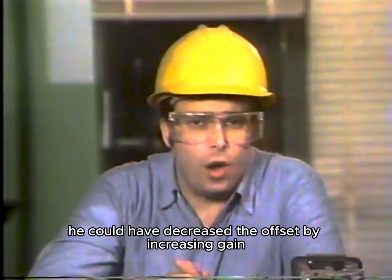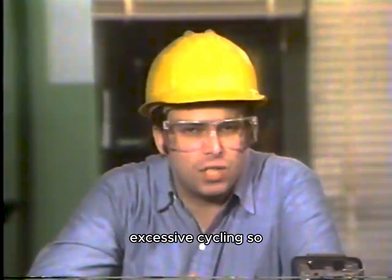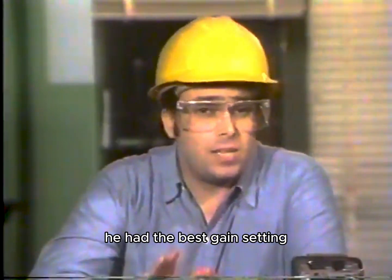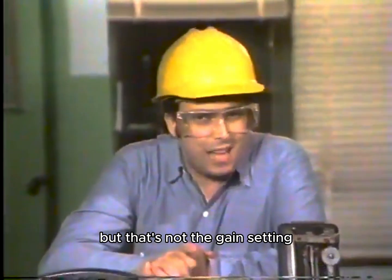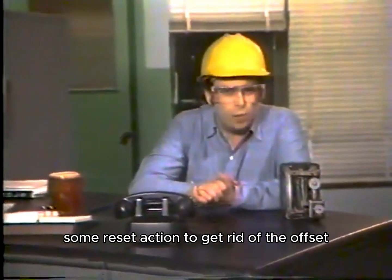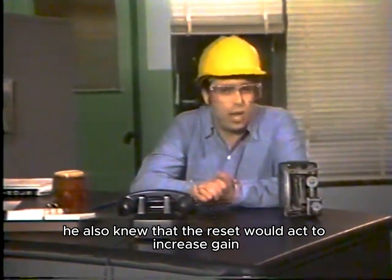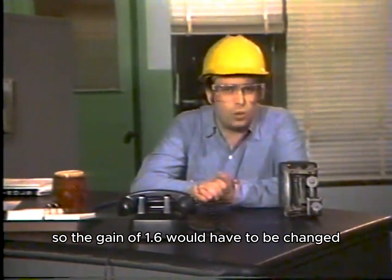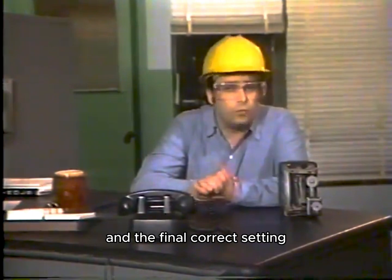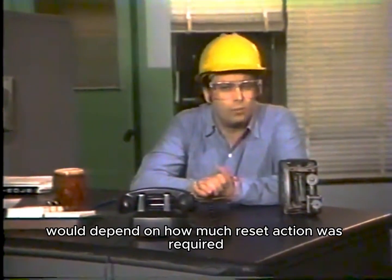He could have decreased the offset by increasing gain, but he knew that that would also cause excessive cycling. So he had the best gain setting for the existing process conditions, but that's not the gain setting he entered into the calibration record. He knew that he would have to tune in some reset action to get rid of the offset. He also knew that the reset would act to increase gain, so the gain of 1.6 would have to be changed. And the final, correct setting would depend on how much reset action was required.